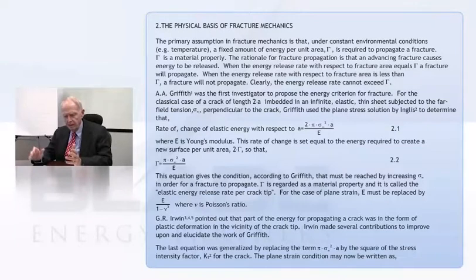And Griffith did a series of very revealing experiments concerning breaking glass fibers, waiting until the surface had been exposed to an atmosphere that had H2O in it, and showed pretty conclusively that the weakening that you saw in the fiber was mainly due to the growth of surface cracks. Now, he could get up to about 10% of Young's modulus pulling on it, and some of the so-called solid-state physicists of those days were predicting that was, in fact, the kind of limit that you should see.